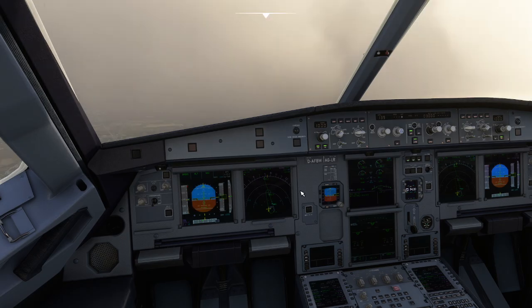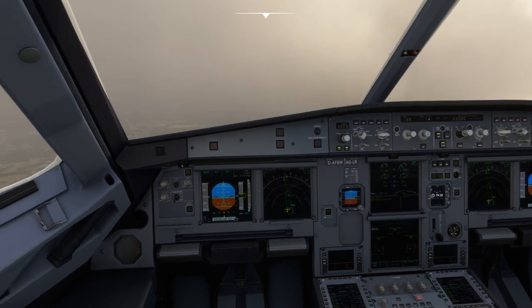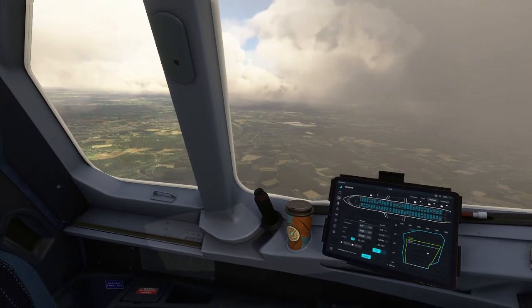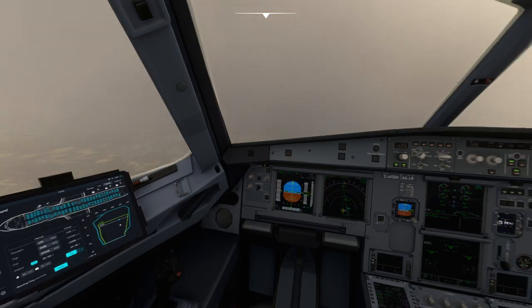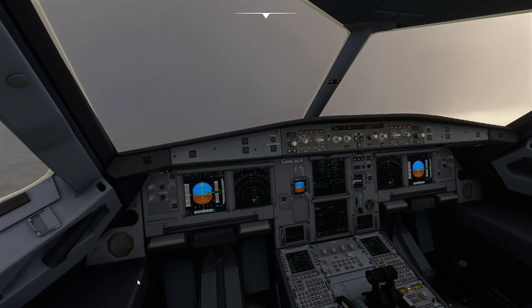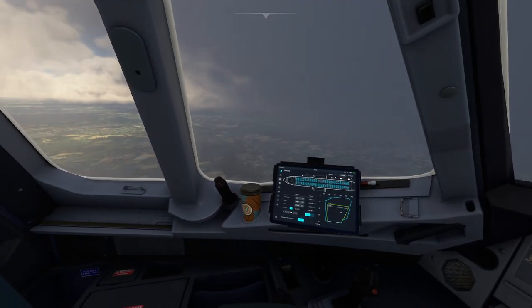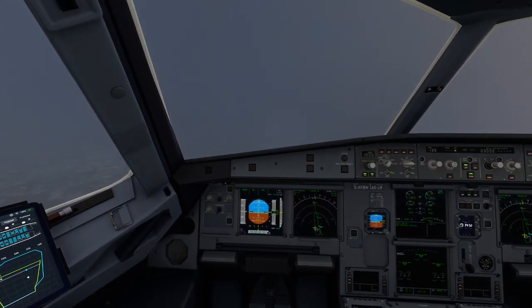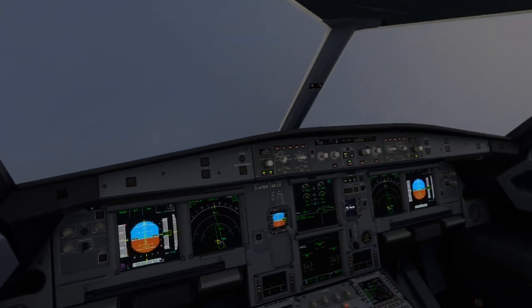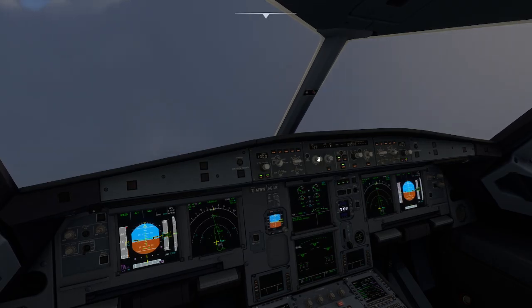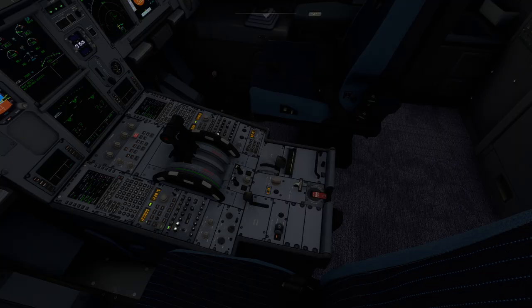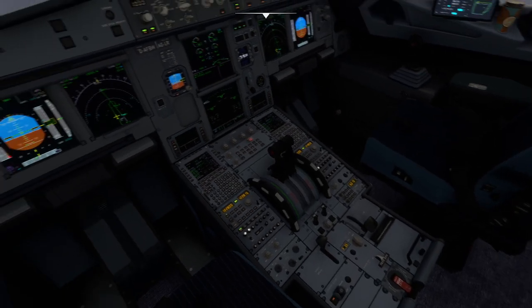I think we couldn't direct on time, so let's try a second time. It's kind of a go around because of the missed approach, but still we have only ground, so we don't have to do anything from the ATC point of view. Our landing gear is down since the speed is low. We don't have to be worried about that. It's about 140 knots. So let's reduce it down to 130 knots. Since we are on flaps 4, we can navigate at low speeds.